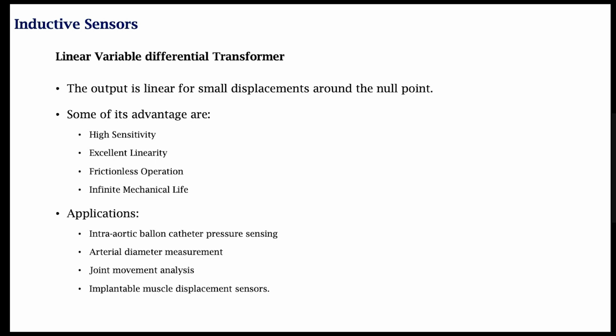You need to use materials that are inert, that do not react with blood, for example, or any other fluid or any other material inside the human body. So we need to use materials that are medical grade. That could be medical grade stainless steel, titanium, platinum, or medical grade polymers, for example, so that they can be used for relatively long term implantation.